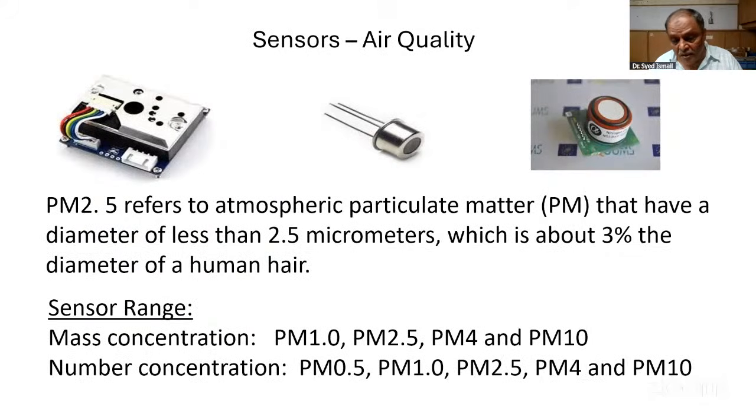Now you have air quality sensors, PM 2.5, PM 1. They use three techniques, you should not get confused. One is chemical based, which is time-period based, 2 years, 3 years. Another is with infrared, and the third is with laser. Now, laser ones are coming at a cost of maybe 4,000 rupees. Very good ones, up to 5,000 rupees. And normal ones, 1,500, 2,000.